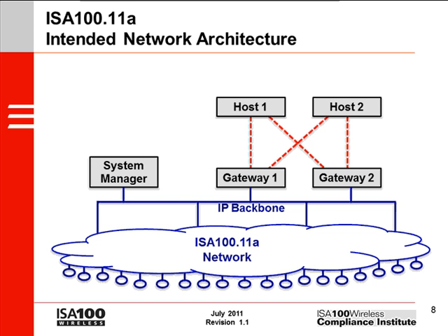In this diagram, field devices are shown as little upside-down lollipops at the bottom, connected to a network that feeds data to hosts through gateways. The system manager to the left side sets up the network but is not involved in the data flow. As we've discussed in a previous webinar, the system manager function in ISA100 is separated from the gateway function. The system manager on the left configures the network, but the actual user data flows to the gateway on the right. As shown here, user applications normally interact with gateways, not with the system manager.